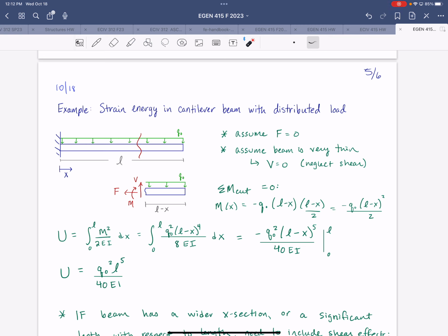Then at a certain point, shear and moment contributions will be equal. Beyond that, the moment contribution will dominate, and pretty quickly it becomes almost completely 100%. So that shear contribution very quickly diminishes after that point.